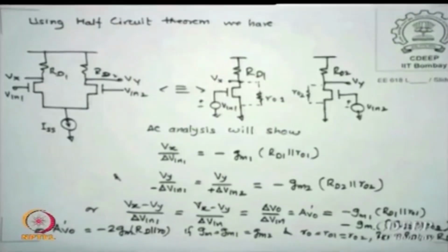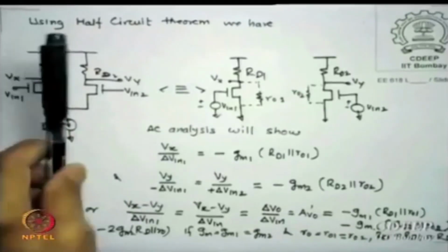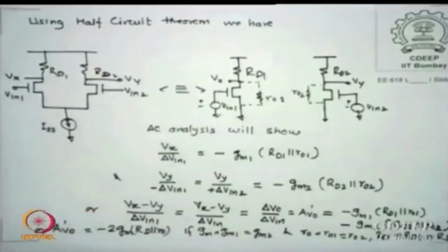Okay, we can do an analysis which is much more rigorous, which we have been doing all the time. There is a second method which I am not showing you; read it from Razavi's book, which is actually a circuit technique. For example, they will assume that one of the inputs, Vn2, is grounded, and then see the influence of Vn1 on Vo1 and Vo2.